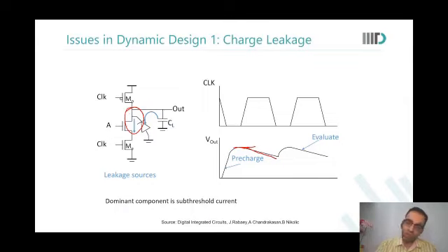So what you need to do otherwise is give the next clock pulse. So clock goes to 0, then again it recharges back. So you need to give this refresh kind of pulse over and over again. This also leads to extra power consumption.